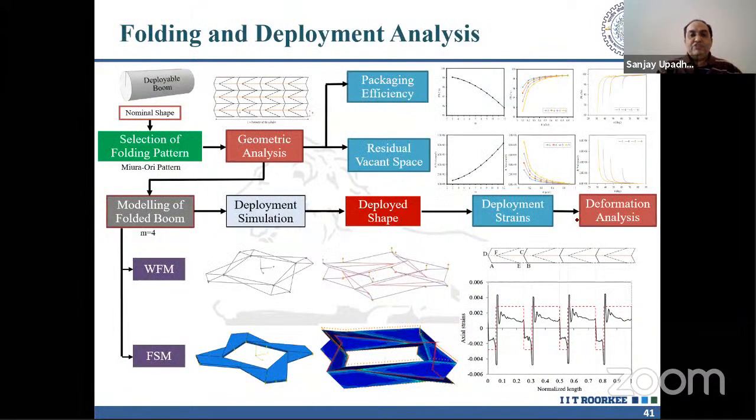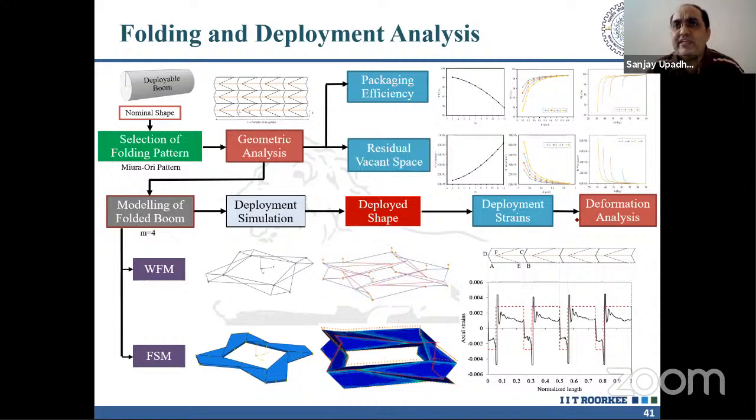Now presently the work is going on folding and deployment analysis. As I told you, folding is much more important: how to fold it so you can easily inflate it without creases, without wrinkles. There are lots of folding technologies, such as Z-fold and origami folding techniques. So which one is suitable from our application point of view? The selection of folding patterns, Miura-Ori patterns.